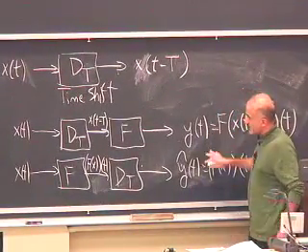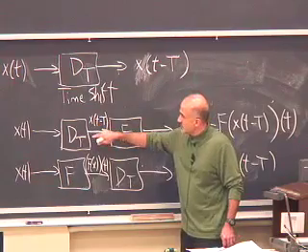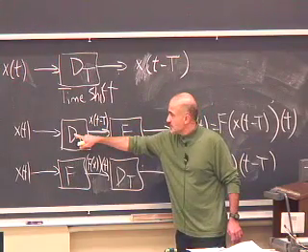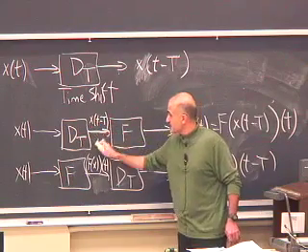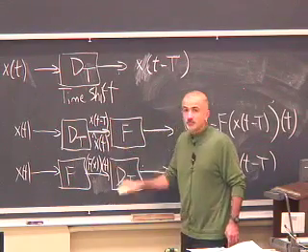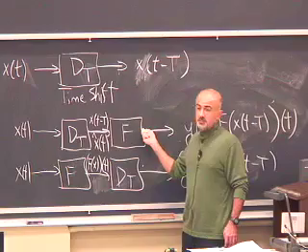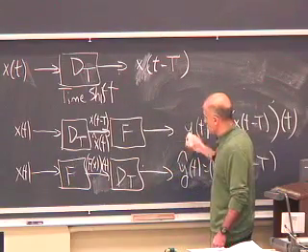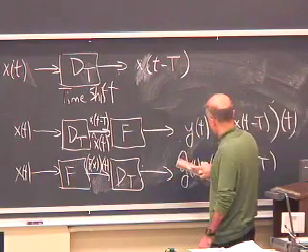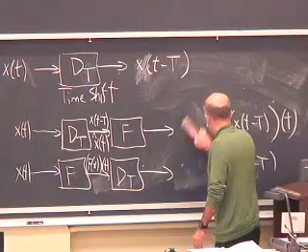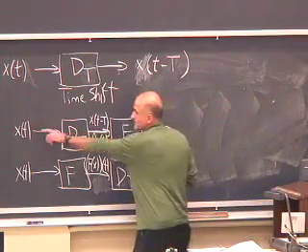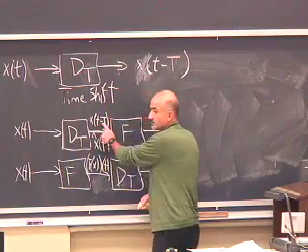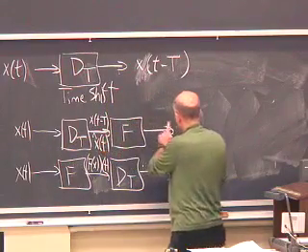Don't worry about the exact expressions. A time invariant system is a system that doesn't care whether you first delay the signal, in other words, create x hat, and then send it through the system. So you get, actually, this should be y hat. Let me clean this up before you get all confused. So a signal that we shifted, we called x hat.